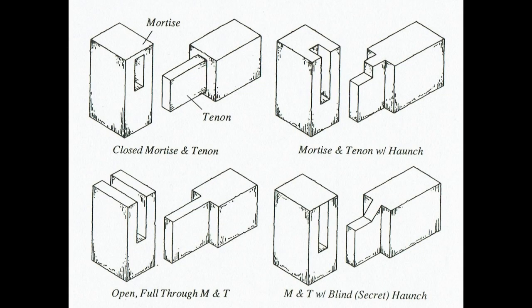Some of the other joints are known as the mortise and tenon, and that's basically where most of the material from one board is completely removed, which creates a little tongue or a little peg, and that little joint will slot into the mortise and create a really strong joint if used in conjunction with a fastener or a dowel rod that slots through that mortise joint and goes through the tenon as well. These will typically be seen in leg additions to tables as it provides a pretty strong joint, but then allows you to change it out with a little bit of brute force later down the line, or easy to replace.